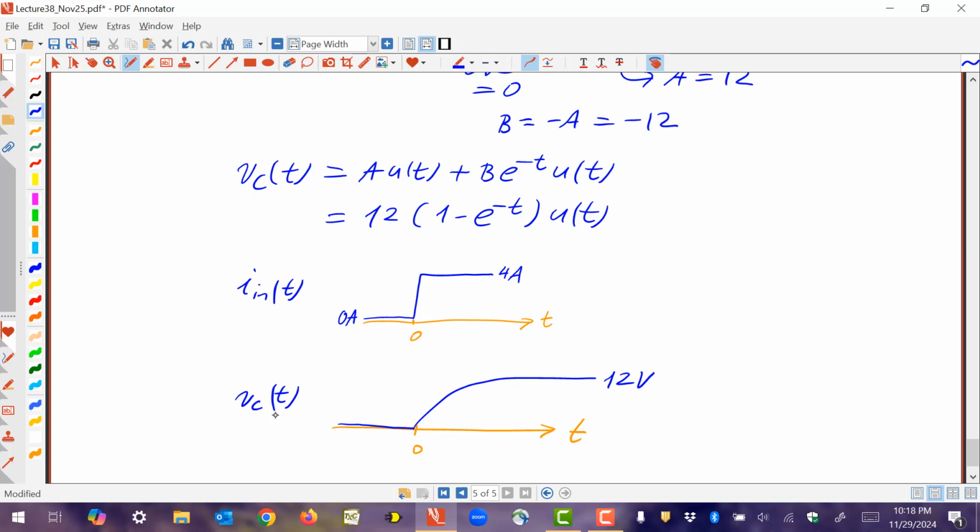So this should give you a feel about how to do at least the simple Laplace transforms for RC circuits. First order RC circuits, impulse response and step response. I did it both symbolically and gave you some examples, and I gave you some sketching, to give you a feel for how this is done. Of course, the way you get better at it is you just have to do more examples. But this is like the starting point, because typically impulse response and step response of circuits are the most fundamental responses you should know for each one of these.